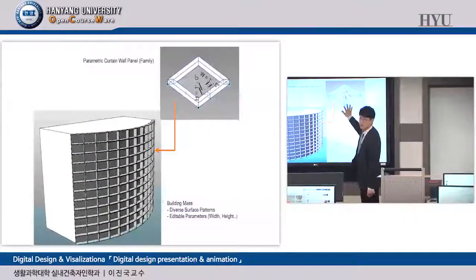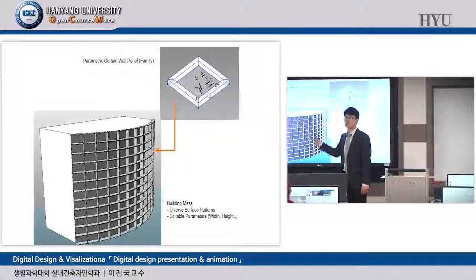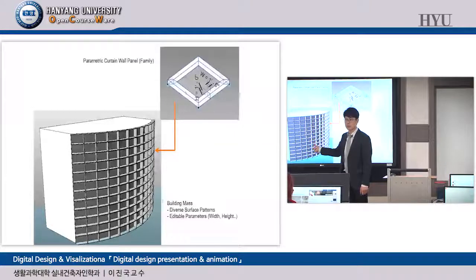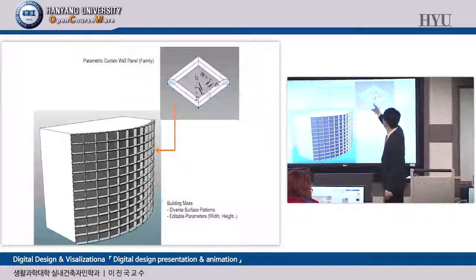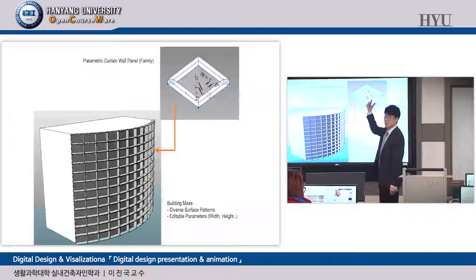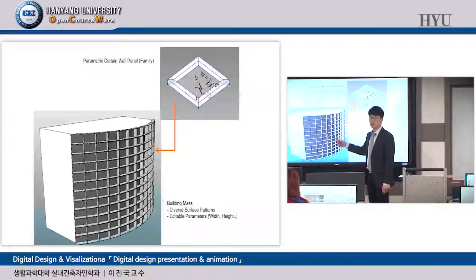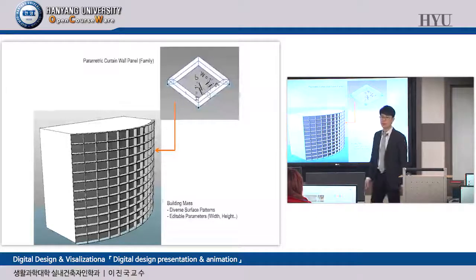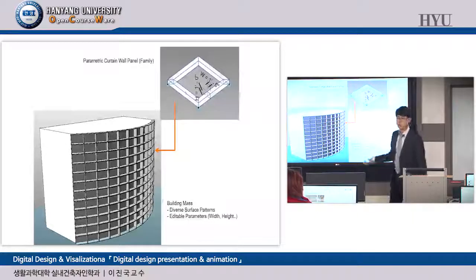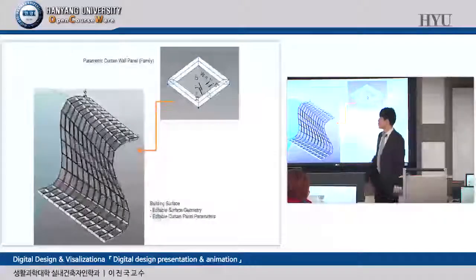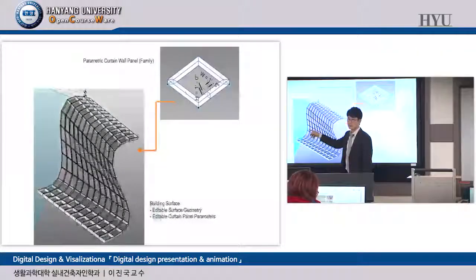You need a part. This part is going to be loaded into your assembly, your project, okay? And then you can get this kind of thing. What if you want to change thickness, depth? Simply change the H parameter and W parameter, and then your final design is going to be updated automatically. What if you change your design surface?